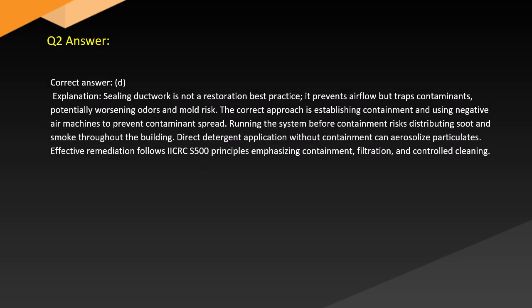Answer. Correct answer: D. Explanation. Sealing ductwork is not a restoration best practice. It prevents airflow but traps contaminants, potentially worsening odors and mold risk. The correct approach is establishing containment and using negative air machines to prevent contaminant spread.